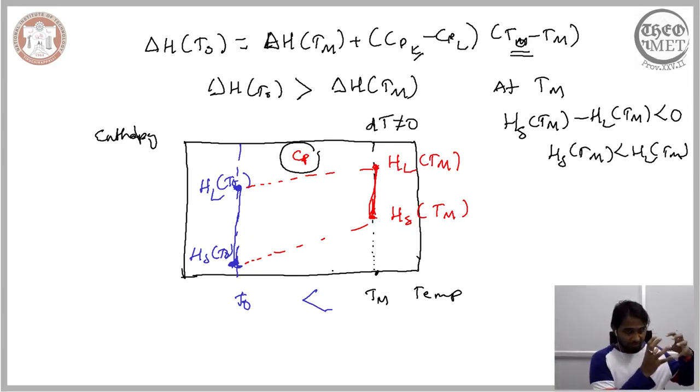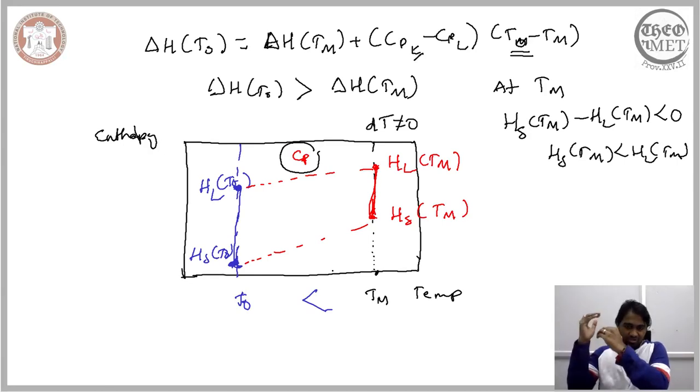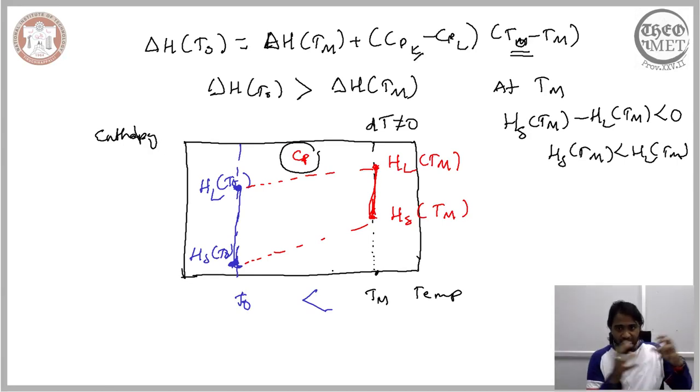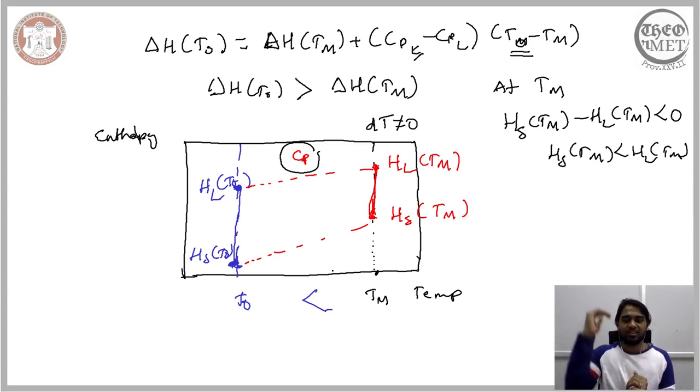So beginning with the first law of thermodynamics, just by considering the first law, we are now able to say that for isothermal solidification, when we reduce the temperature or hold our system at a lower temperature, the driving force for solidification is higher than when we hold the system at a higher temperature.